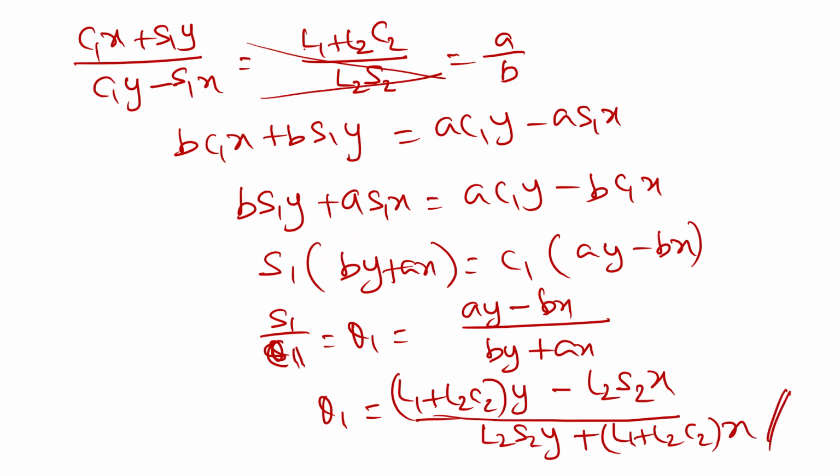In the previous slide we have seen what theta 2 is. In this way, we'll be able to find the joint coordinates. So theta 1 and theta 2, we found them using some formulas with the help of x and y. The x, y coordinates are applied in inverse kinematics to find the formula for theta 1 and theta 2 using the algebraic method.